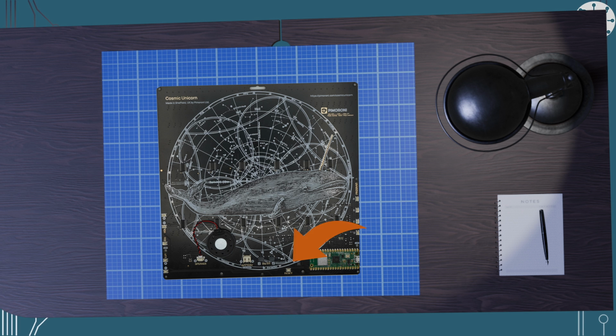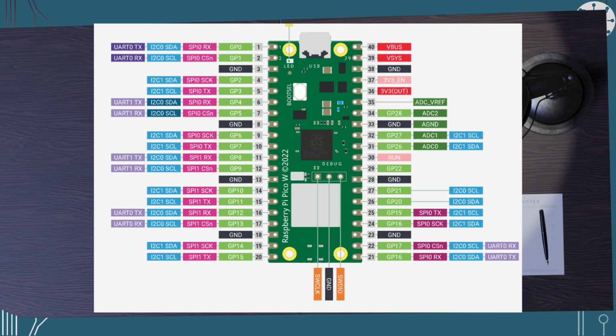Now there is a battery port on the back of the Cosmic Unicorn, and in a moment of complete madness I thought, I can power it via that. But no, of course you can't, because the battery is providing power to VSys. A USB device also needs to get power, and it's connected on VBus. And there's a diode between VBus and VSys, so no power goes backwards. So I had to think of a different way of getting power to it.